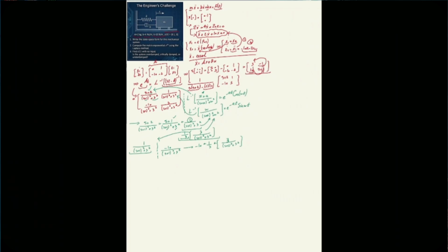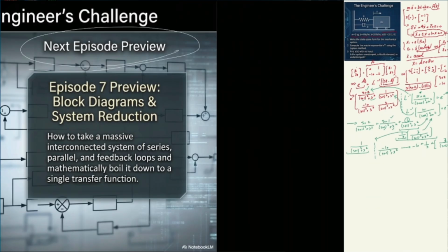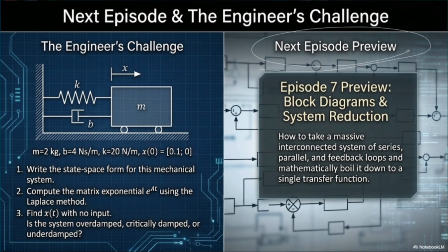So that was the final slide of this chapter. As you just saw, we talked about many different concepts, but the very important thing I wanted to emphasize is that your system has some limitation. We cannot use the methods we knew about, such as state space and the Laplace transformation, if we don't have a linear system. If we have a nonlinear system, we have to use another method. That very important method was the Euler method. Then you have to choose the step size, and you should be very, very careful about that.